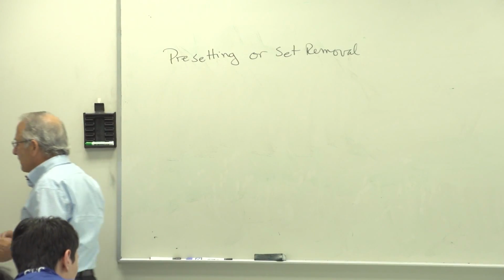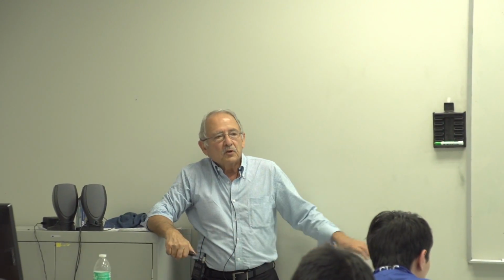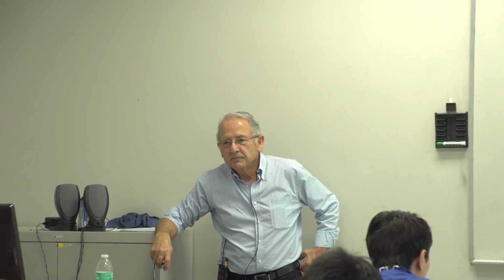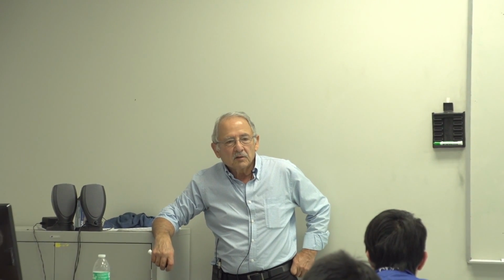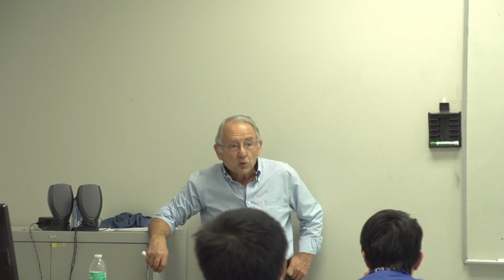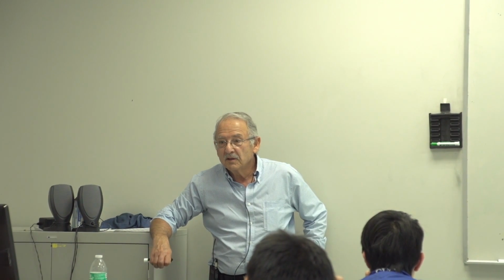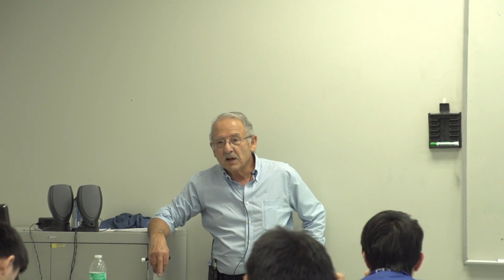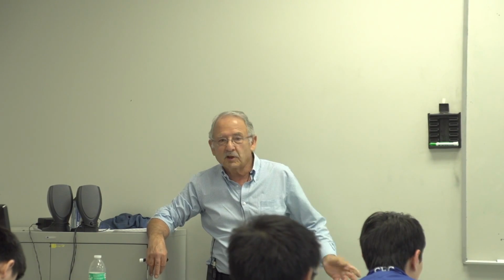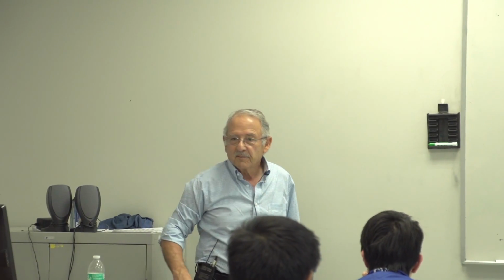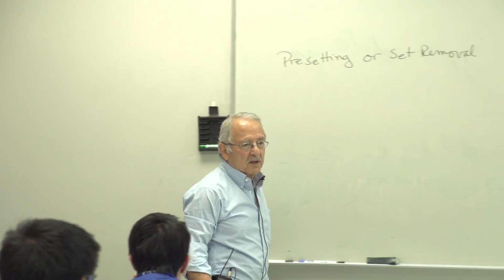Now, on the face of it, those two appear to be contradictory. Presetting sounds like something we're doing to the spring. Set removal sounds like something we're taking away from the spring. But they both mean the same thing.